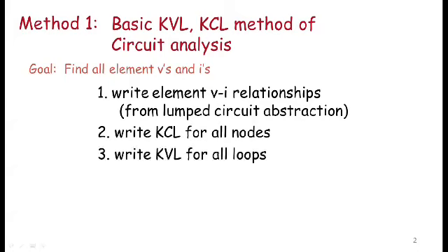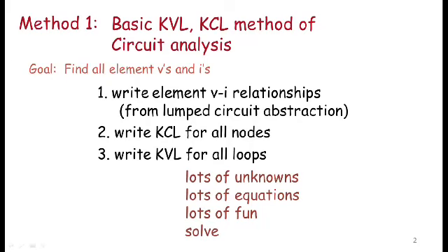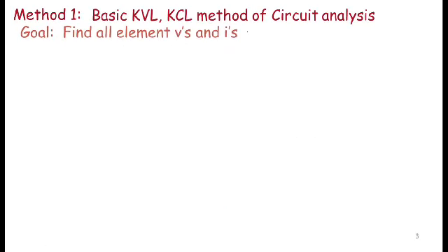Then, as a third step, you go through the loops one by one, and you write KVL for each of the loops. Notice that each of these equations is a very simple equation containing simple algebraic expressions of the currents and the voltages. Now, you will end up with lots and lots of equations, and you will have lots of fun solving them. Well, let's take a look at an example.